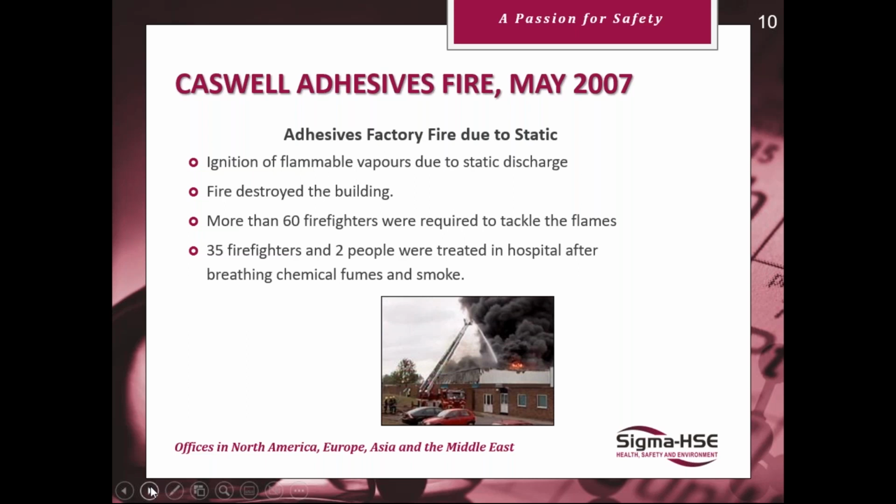One of the problems that we find when working with adhesives is that a lot of them are insulating. They're very insulating in nature, and they often cover the floors and the equipment, and it results in isolated people and equipment. And this can often result in a static discharge. I'm not sure what happened in this one, but I would assume from experience that this is probably the cause of it.